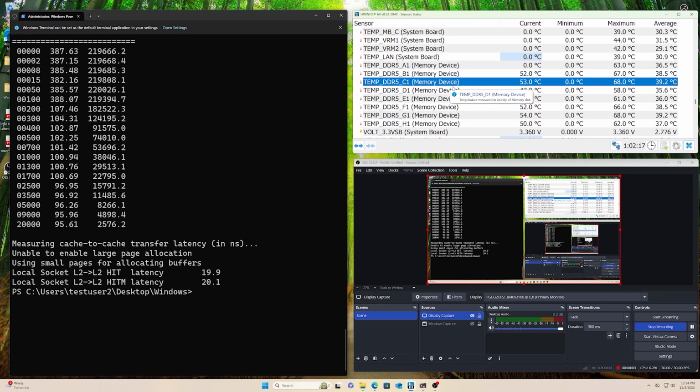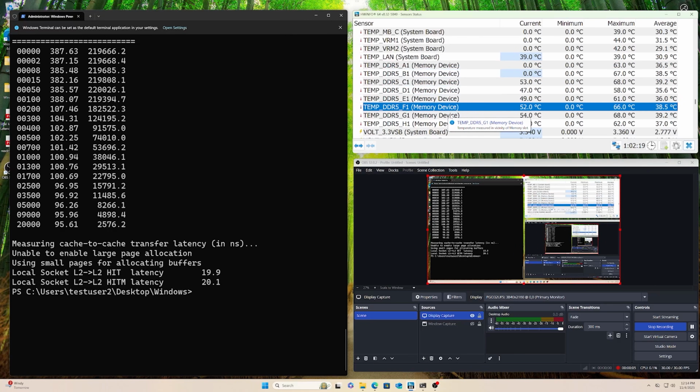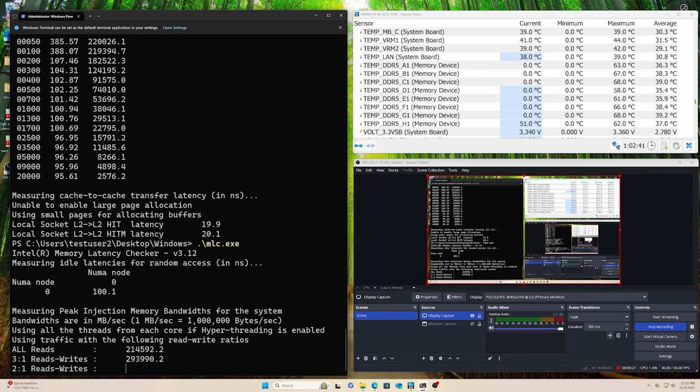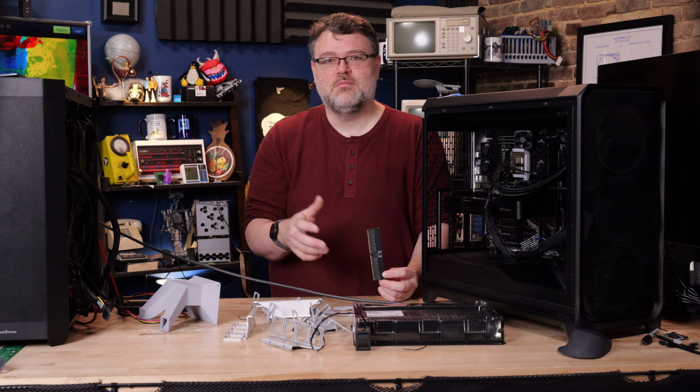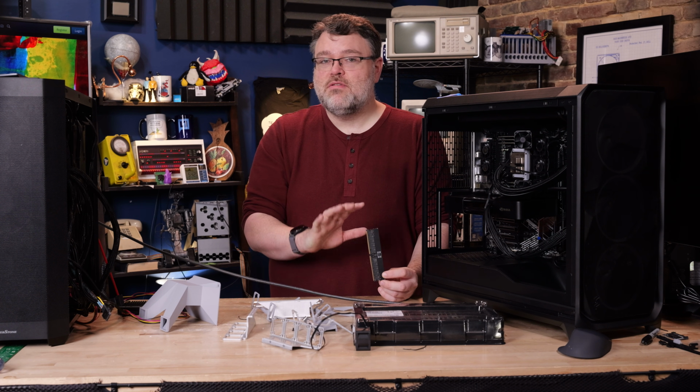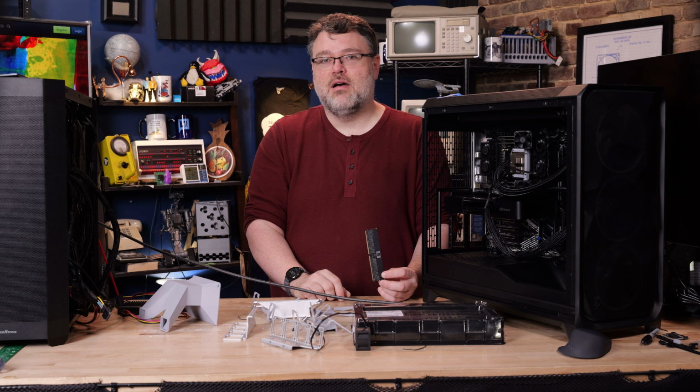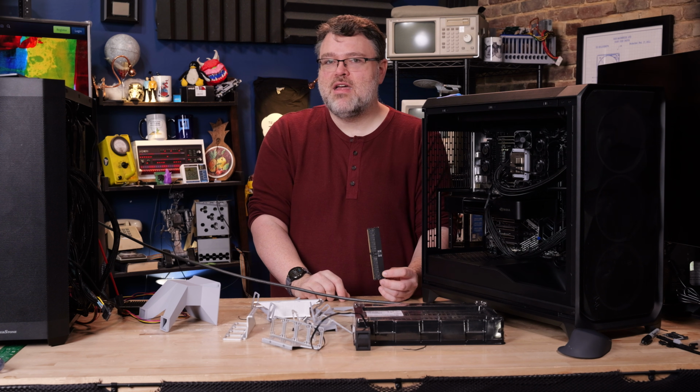On the ASUS boards, I could get the throttling to work after hitting the clear CMOS button and then loading optimized defaults in the BIOS, but not changing anything, and then immediately testing. But then after I did a soft reboot or just reset the system, it stops mysteriously. Not even loading an EXPO or XMP profile. I thought I was losing my mind because even doing that doesn't actually guarantee consistent throttling behavior.